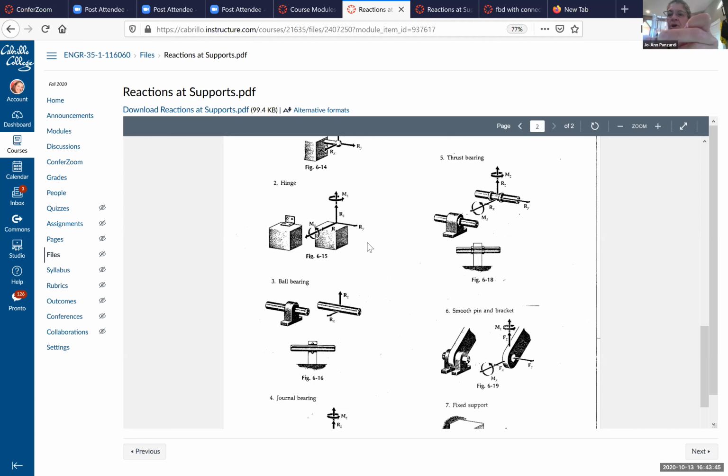On a hinge, can these 2 objects resist a force in the X, a force in the Y, and a force in the Z? Yeah. I can't move these 2 pieces that are hinged together relative to each other in translational motion. What about a rotation? Certainly these 2 pieces can rotate about each other along the axis of the hinge, but otherwise they cannot rotate in that direction and they can't rotate in this direction.